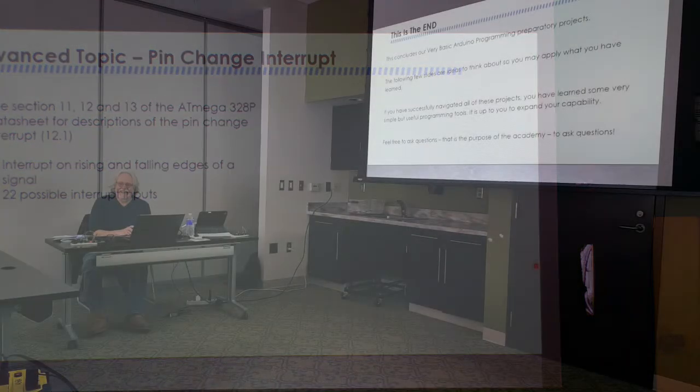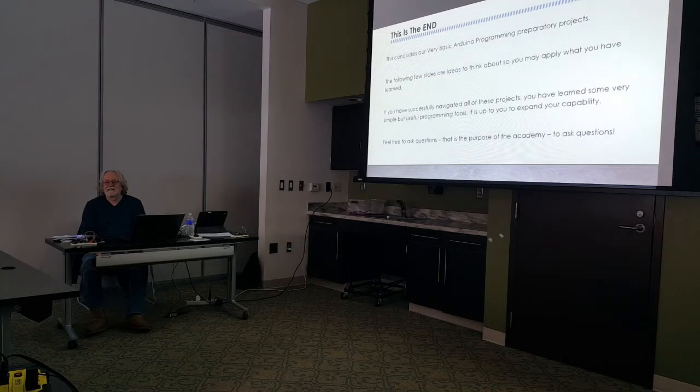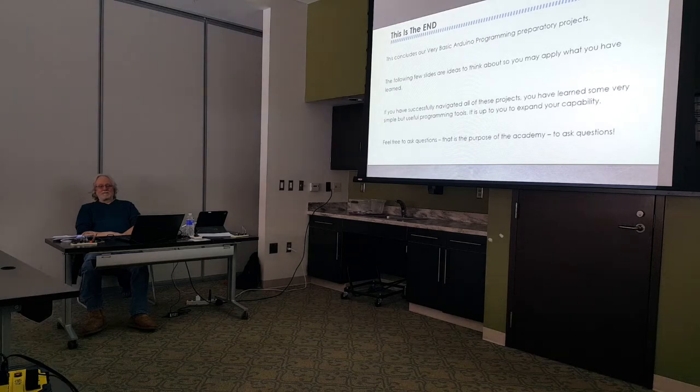So, a question about the interrupts, the edge triggering. You could start the timer against the occurrence of the edge and measure frequency, like if you were building some kind of a decoder. Right. Well, go back to the timer. You use the input capture. On a zero crossing, you would trigger the input capture to read a value from the timer, and so you save that value away.